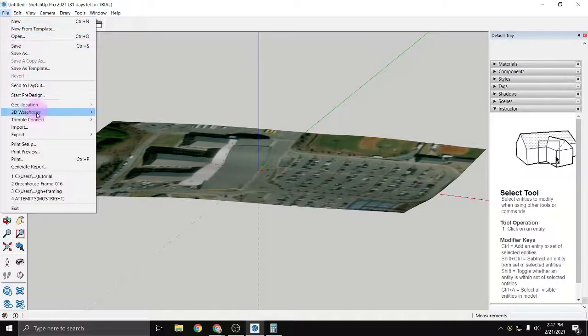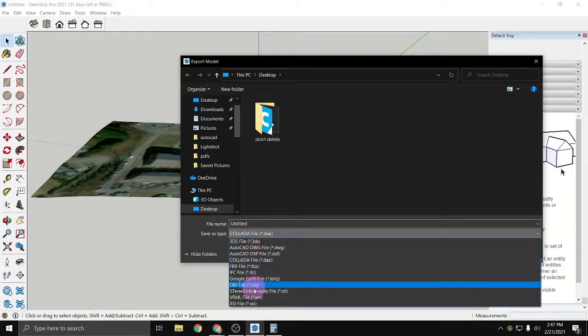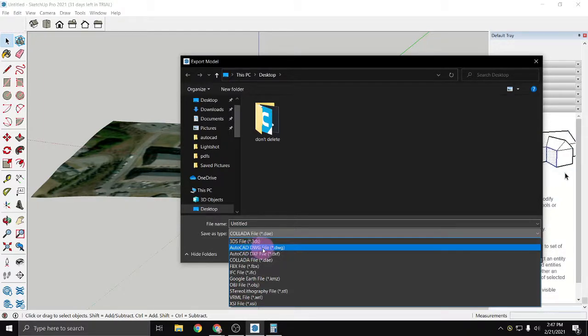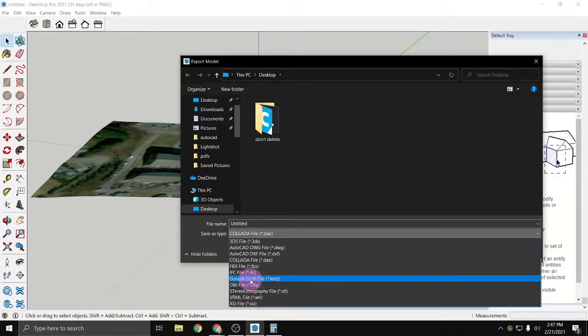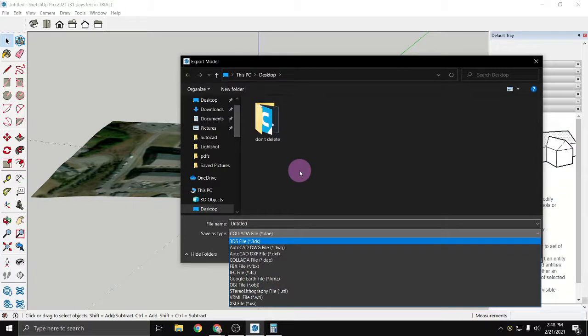And then we can export it as a 3D model. And I can't remember, I don't believe we do it as a 3D DWG. We either do it as an STL or an OBJ for Revit, but I'll get to that once we have to cross that bridge in Revit, because if I open up Revit right now, it'll probably freak some of you out, but I promise Revit is not a hard software. But we can export it as that 3D model and then use it to just kind of help make our site in that software that much easier.